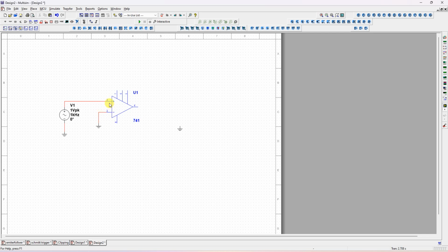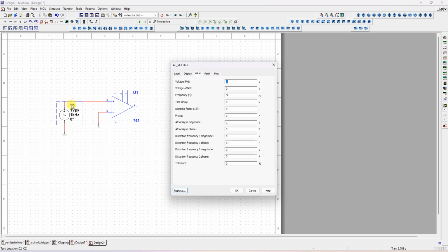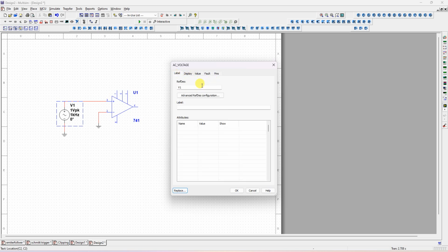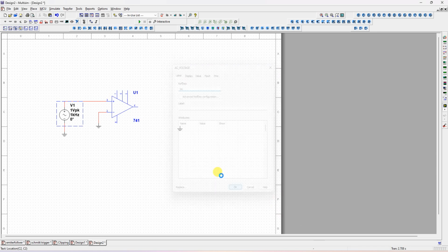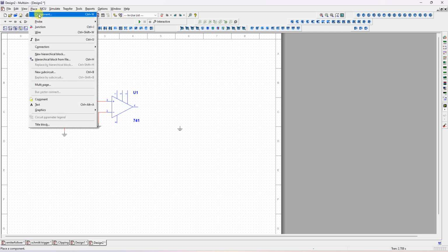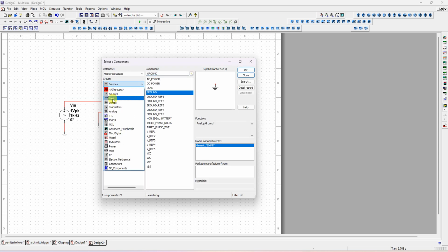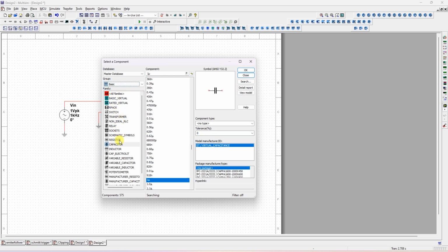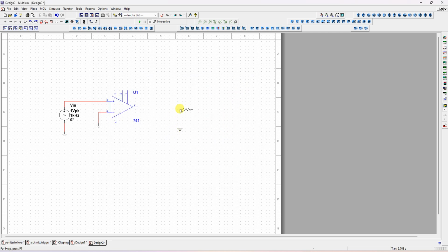The Opamp has two inputs, and we are checking whether the input voltage, this is the input voltage. I can change the label. I'm clicking on V1. I will change the label to input voltage V in. Okay, input voltage V in. Now I will connect one RL here. Place component. I will place one resistor. The basic resistor is there. This we can consider as a load resistance.